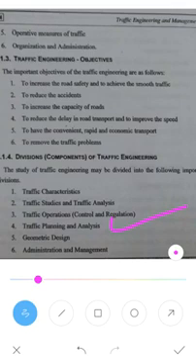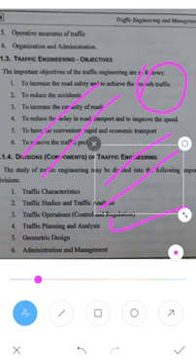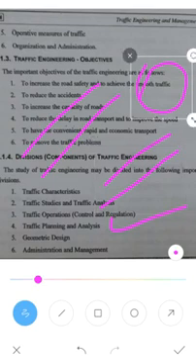Next is the geometric design. In geometric design, different types of design are used, such as rigid pavement or flexible pavement. Where the circle should be made, what the width of the road should be, where the divider should be provided, whether a divider has to be provided or not, whether the road should be 2 lane, 4 lane or 6 lane, whether an expressway can be provided or not, whether that road is connected to the outer ring roads of the cities, or whether in the future the road can be extended or not. All those will be planned in the geometric design.